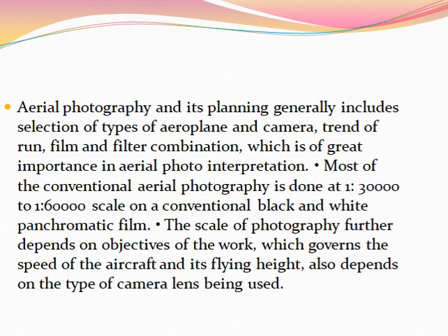For extensive ground coverage, satellite imagery is most useful. For more specific and detailed information such as geotechnical studies, mineral exploration, groundwater surveys, land use planning and town planning, large-scale photographs are used, such as 1 to 50,000 to 1 to 10,000, which are widely used and most suitable.